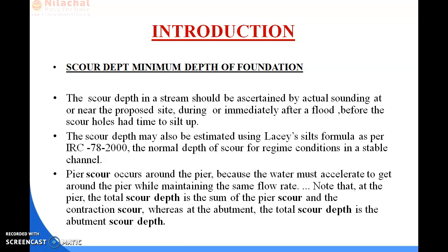So again I want to repeat, what is scour? Bridge scour is the removal of sediment such as sand and gravel from around the bridge abutment or piers. Okay. And scour is caused by swiftly moving water which can scoop out scour holes and compromise the integrity of a structure.